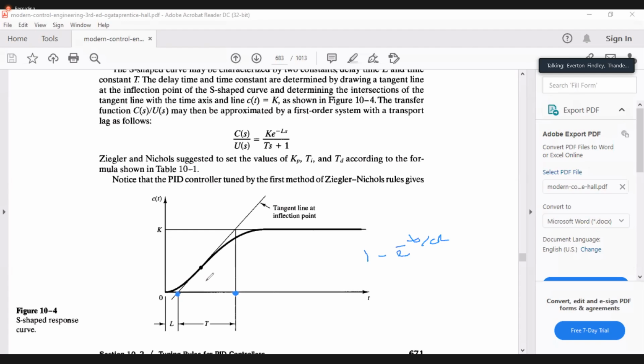The first T is the time constant, that value after the lag time, and that would have been the 0.2, that would be the 4.9. But no man, remember the time constant is a big T. So what we just found is the time constant and not the lag time. We found the time constant of 4.9, which happens after the lag time.